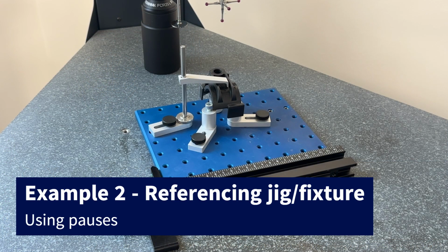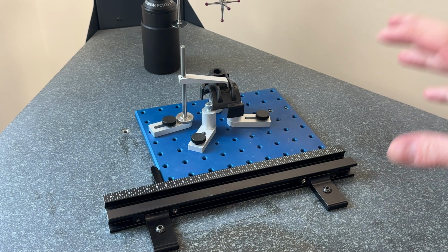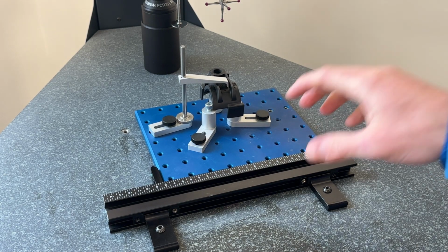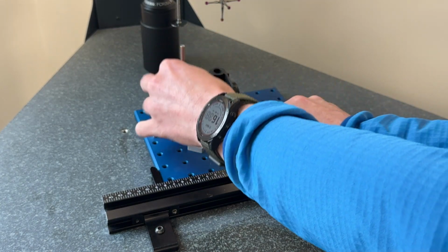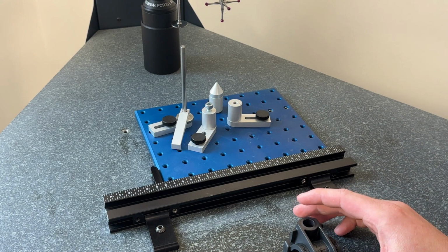This is example number 2. And in this example, we're going to showcase the ability to use a jig or fixture as the reference system. So typically, injection molded parts or casted parts, you might not want to reference off the part itself, you might want to actually reference off the jig or fixture system, or even a mating part.